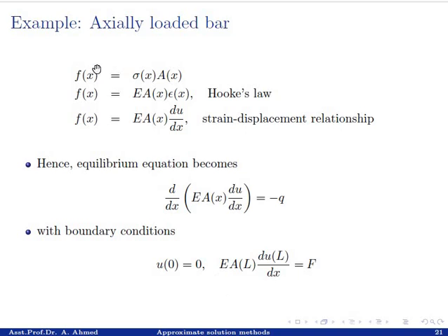where I know that the internal force F of x is nothing but the stress inside the member times the area over which it is acting. And from our definitions, the stress is the Young's modulus times the strain, and incorporating the definition of strain, which in this case is the strain in the x direction, simply du over dx. So now the internal force F of x equals E A of x times du over dx.